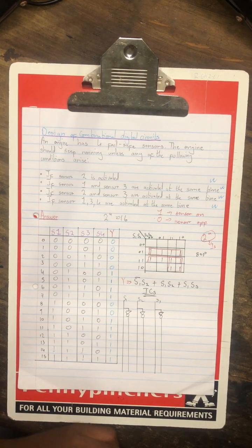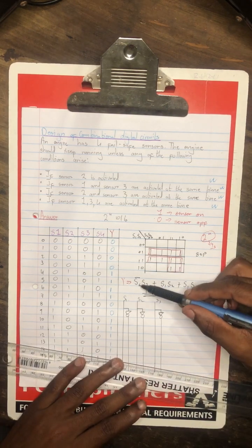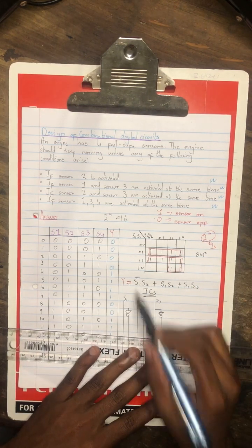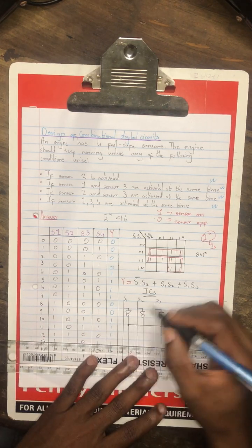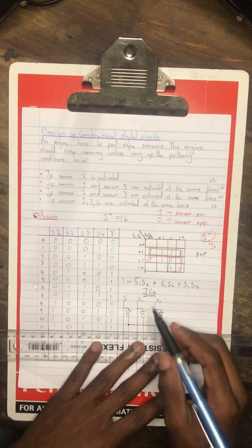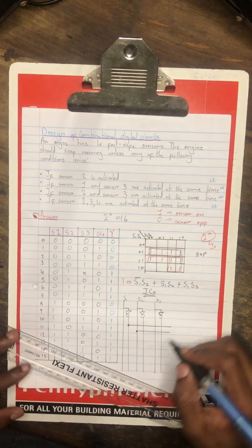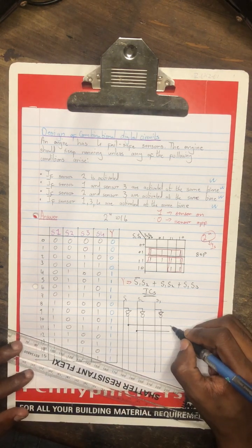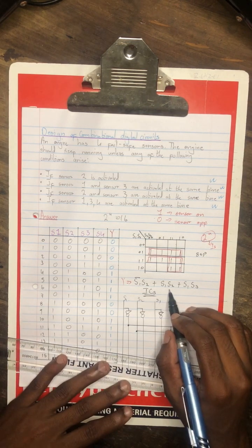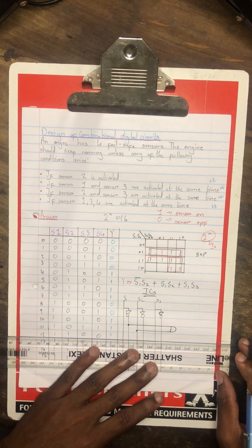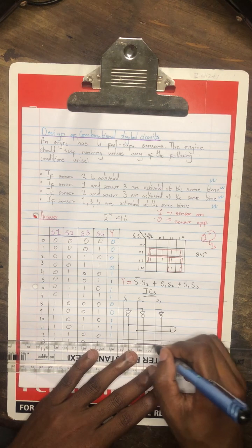And we are going to tap in from any of this. So we go down to condition number 1, we say sensor 1 and sensor 2. But sensor 1 has a bar, so we tap in from here, sensor 1, which has a bar right here, and sensor 2, right here. And it's passing through an AND gate. And then we come down to sensor 1 and sensor 2 being ANDed together.